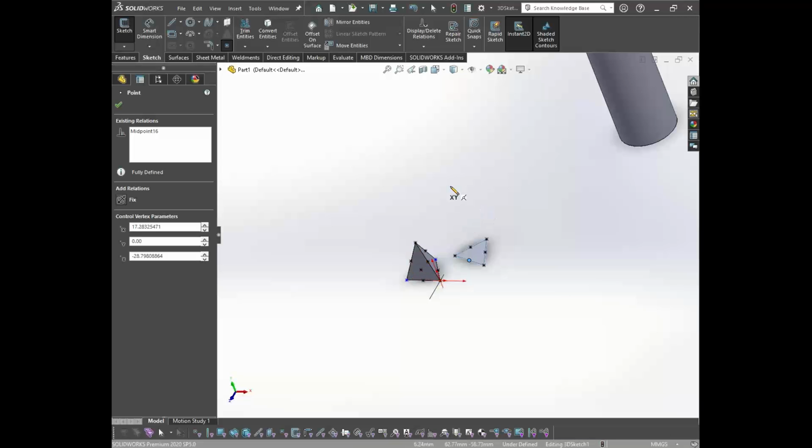So I assume that you have understood what I have tried to explain to you. What exactly is the element? What are the solid elements, shell elements, and beam elements? What are the subgroups? There are linear or draft quality elements, then there are parabolic or high quality elements. When we increase the order of the elements, when we change it from linear to parabolic, it will capture more of the geometry, more of the small features that are involved. It may be curvatures, small fillets that are there, and we can calculate more accurate results.